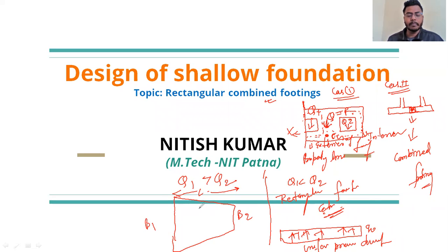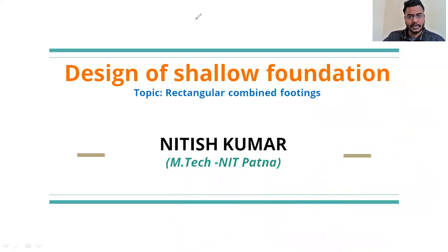We cannot make the center of gravity lie on the resultant of the loads, and the pressure distribution will not be uniform. So for that case, we should go for the trapezoidal combined footing. In this lecture, I'm going to discuss only the rectangular combined footing. In the next lecture, I will discuss the trapezoidal combined footing. Okay, so let's start and discuss this rectangular combined footing.